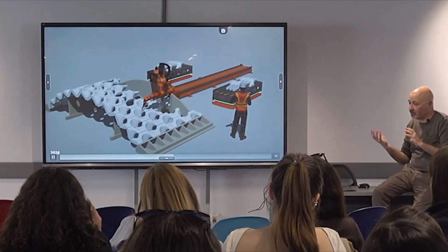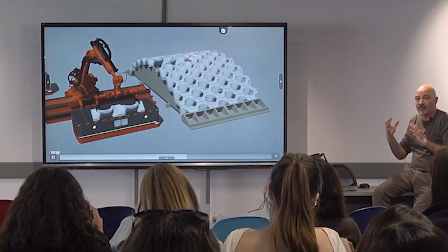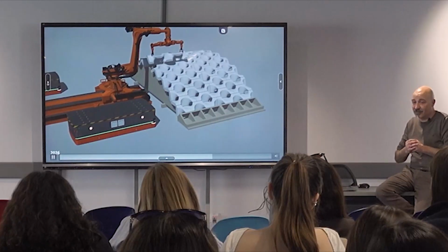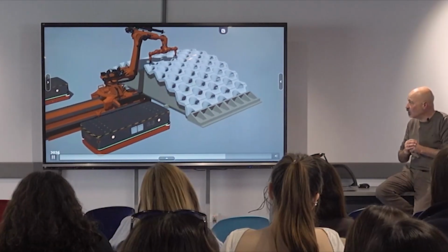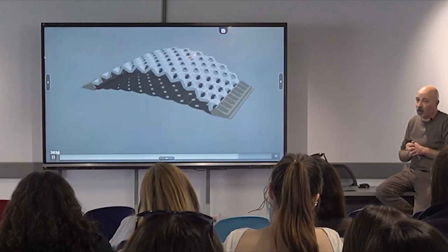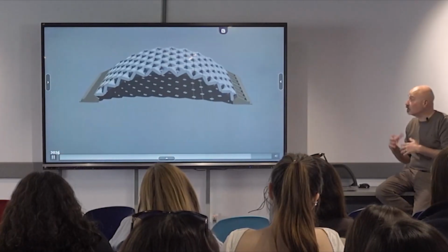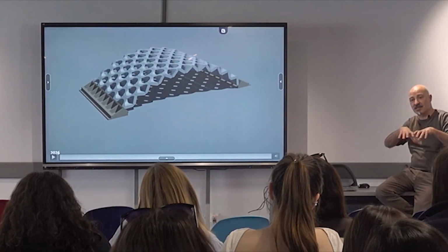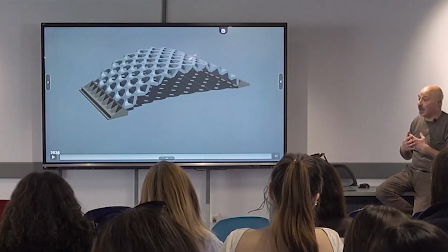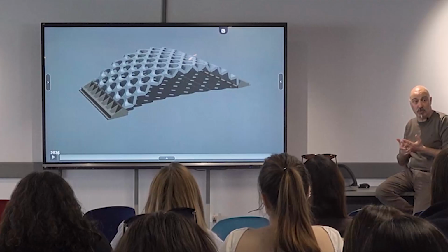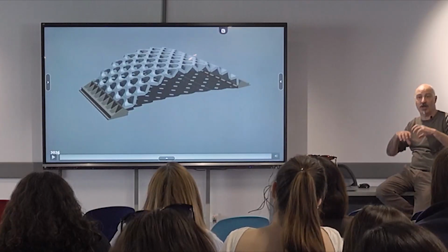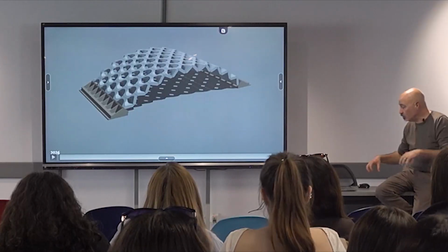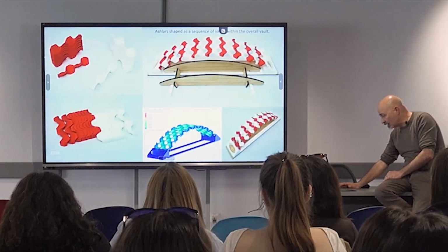So here we have the traditional way to build a vaulted space, because they are in compression only, using the robotic machine, because we think that the future of stereotomic vaulted space is linked to the robotic assembly. That is a very simple assembly because it's a cylindrical vault, but at the same time the problems are very hard to solve, because of the end effector taking the block, a lot of crash tests between the blocks during the movement, a lot of problems are coming.